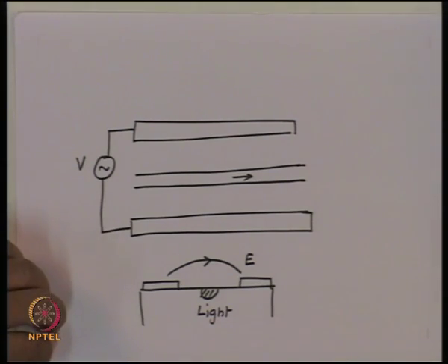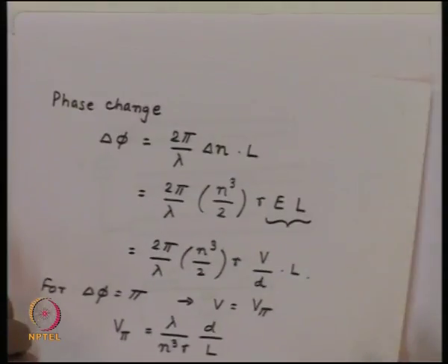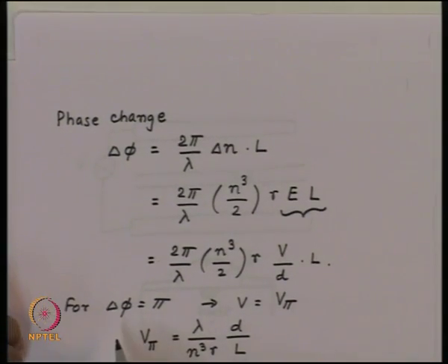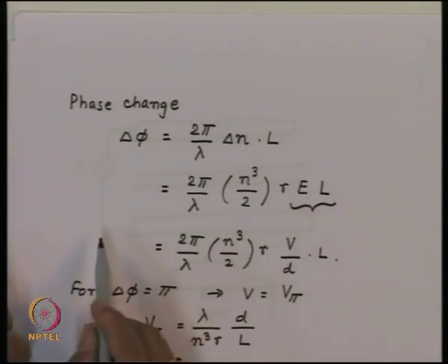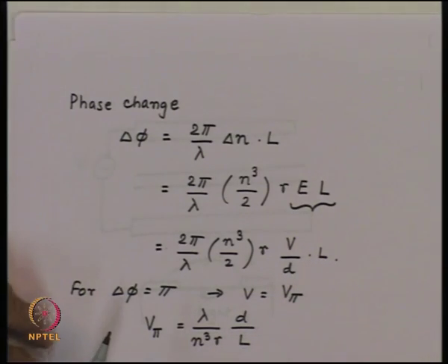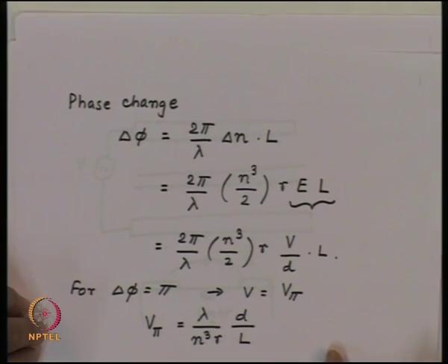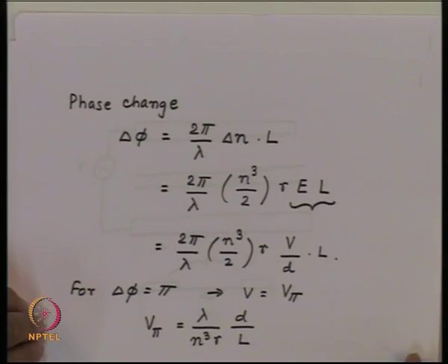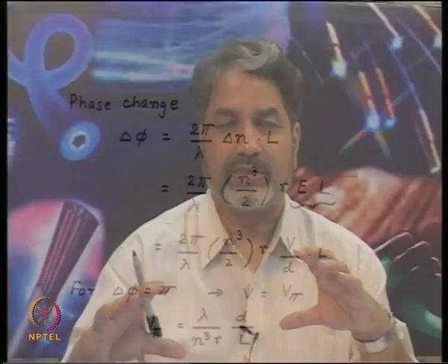In the ideal situation, as we increase this length, the phase would have accumulated linearly as a function of length, but that does not happen because the voltage signal which travels on the electrodes has different phase velocity than the phase velocity of the light which is confined inside the substrate.